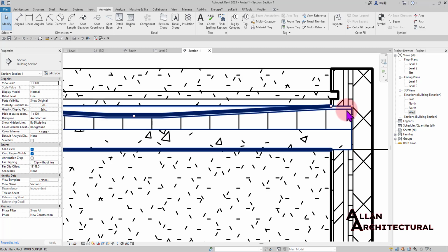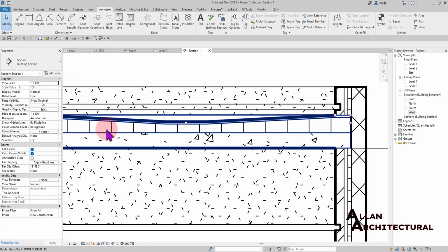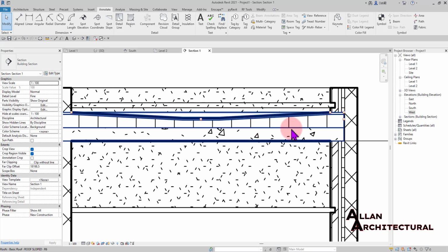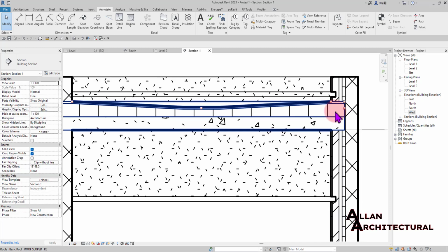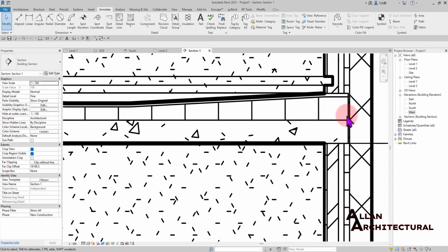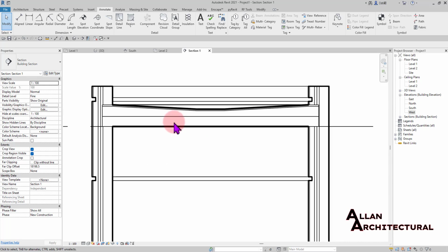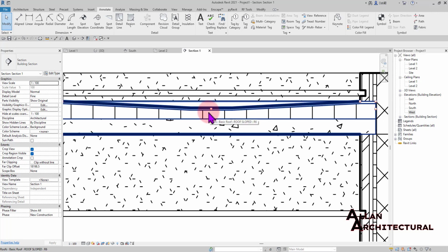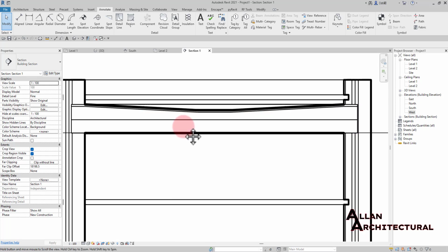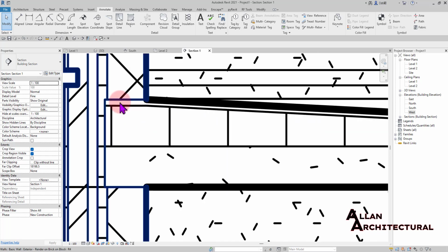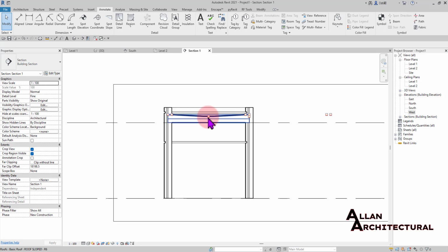Since I knew my rigid material, I can't slope that into my concrete. I can't slope that into the structure part, which is the concrete part. So I need to make sure I slope that just on the insulation material I had on top of that roof. That is why we needed to check the variable for the rigid insulation material, because we can't slope into the concrete structure. And that is why I also gave it a slope of -100. So it slopes in there. I can give it a slope of -200, but then you notice we had some 30 millimeters, which is perfect. So you need to make sure you just have a little gap on top as well, which is kind of perfect.